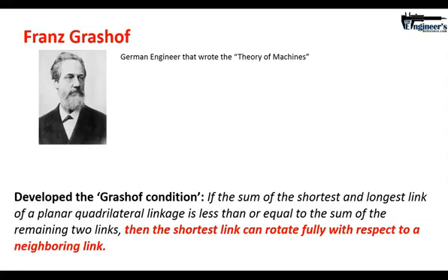So he is describing a 4-bar linkage, and that is very important in mechanical design. It is a very important mechanism. This shows up in all sorts of mechanical devices, from your windshield wiper to your steering mechanisms to several things that I probably can't think of. So this is the whole idea behind a 4-bar linkage and how you design 4-bar linkages. And this is the equation written out. So you've got S plus L, short link plus long link, should be less than or equal to the remaining 2 linkages.